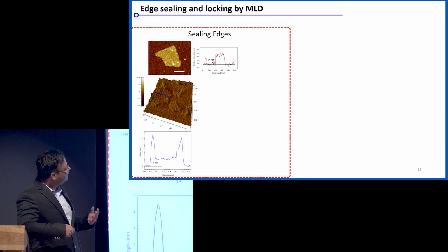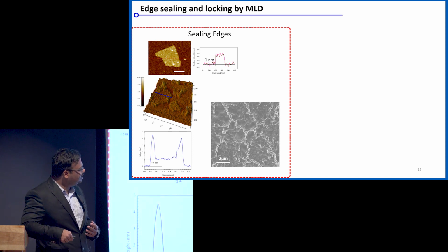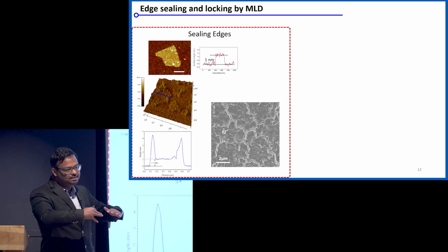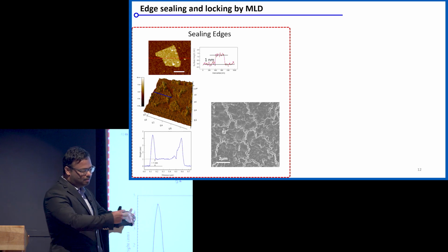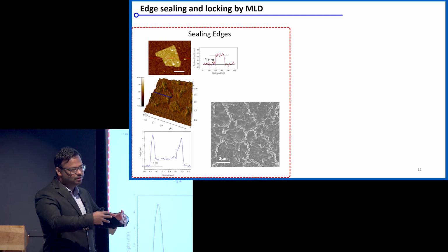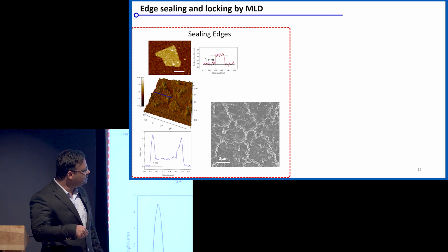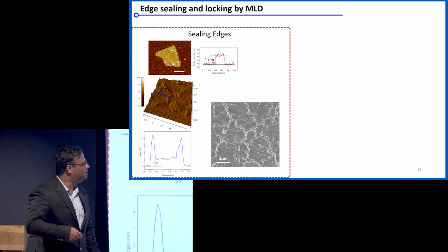So this is one thing, and if we have a stacked graphene oxide membrane, this translates to something like this. You will have the graphene oxide flakes on the top surface, and this material will go along the edges of those flakes to stitch them together. So you have small pieces of graphene oxide flake as if you are stitching them together into a large continuous sheet. And there would be pores within this structure which allow the permeance of molecules through them.